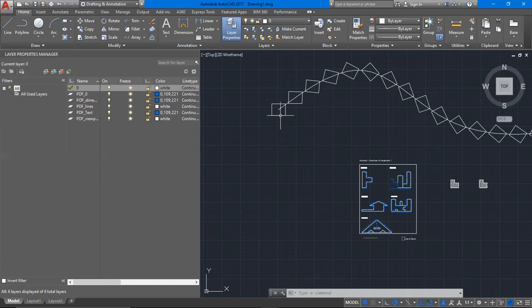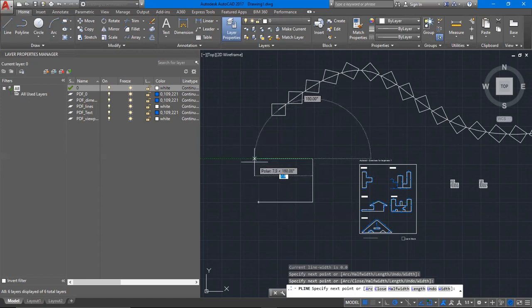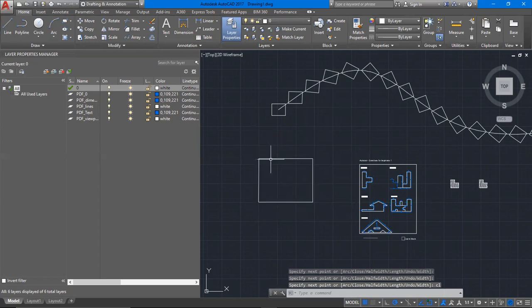You can explode other things. You can explode a polyline. If you drew something using a polyline, for example, if I draw some rectangle here using polyline, let me close that one there. You realize it is selecting all lines. So if I want to explode those lines, I can just type X, select that object, and hit enter. You realize now it will be selecting individual lines because that polyline has been exploded. So that is how we explode arrays, and that is also how you explode polylines.